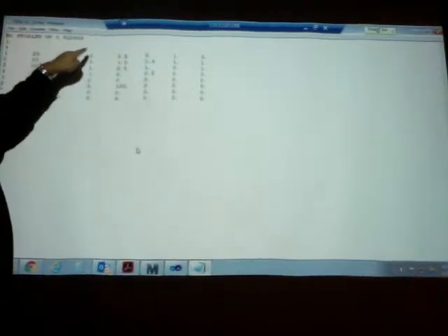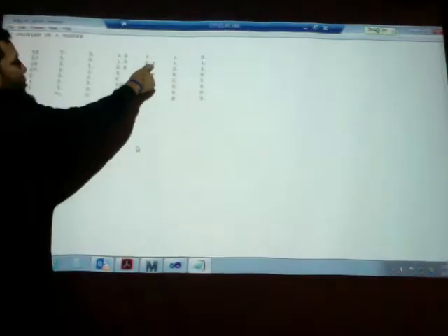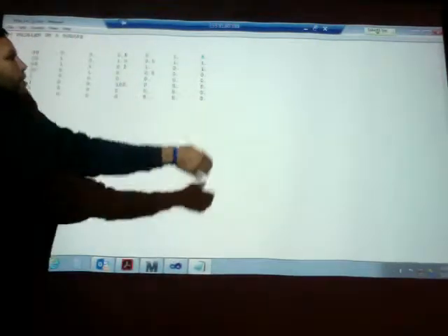Segment 1 has 20 elements, from 0, 0 through 0.5, 0 to 1, 0. That's the bottom of the square. Spline 2 has 20 elements and goes from 1, 0 through 1, 0.5 to 1, 1. That's the right side wall. So it does the square on a counterclockwise basis.